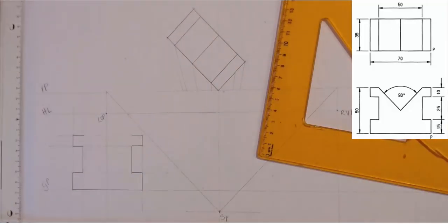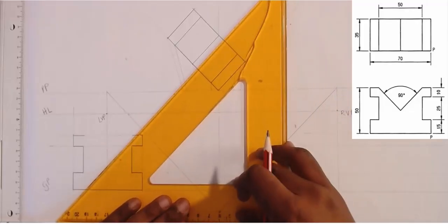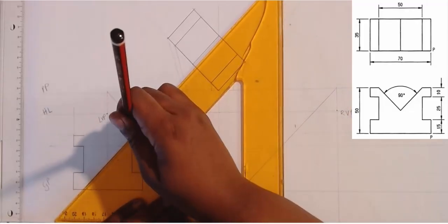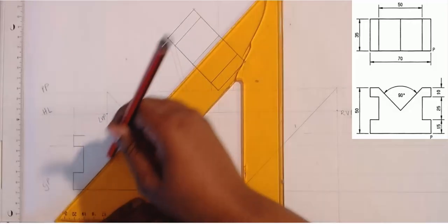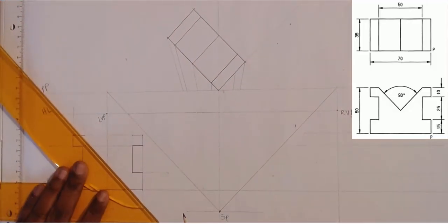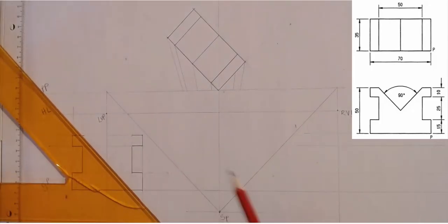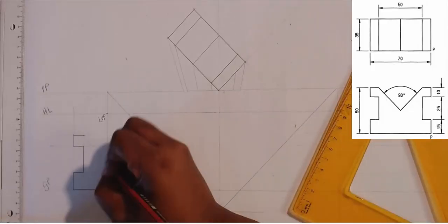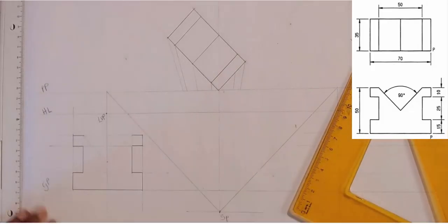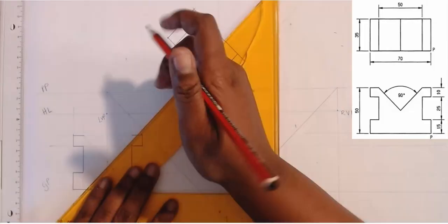Now we're shortening the middle part. The middle part, they say that angle is 45. That means it's 90 degrees. That means I'm going to use my 45 from this point right here, and I just draw construction lines where the two meet in the center. Where they meet in the center, that's where my drawing is going to be.